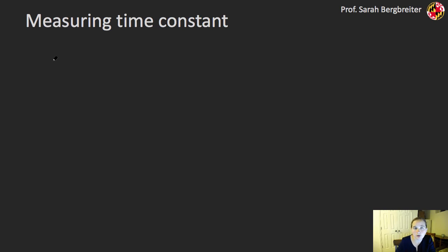In this case, you've already done this in your lab, so you might have some V_in from a digital I/O pin on your Arduino. You have some resistance, and then you have, in this case, your capacitive sensor to ground. Now this node here you'd have going to an ADC pin on your Arduino because you'd want to be able to measure the voltage across this capacitor as it charges up and as it discharges.